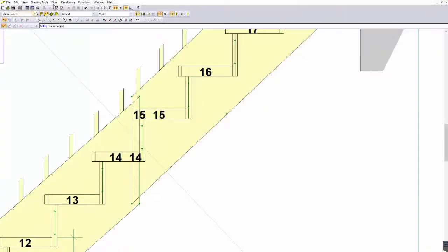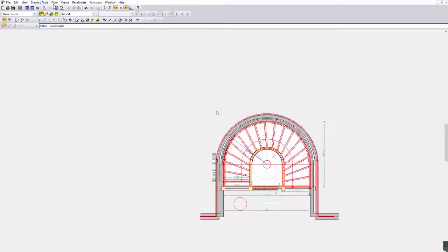The great thing about this is that for this particular stair, every one of these treads is different. So when I would program before we had Staircon, I'd have to pull each of those treads off by hand and program in AlphaCam. This processing for production is much quicker as far as outputting G-code for these parts.